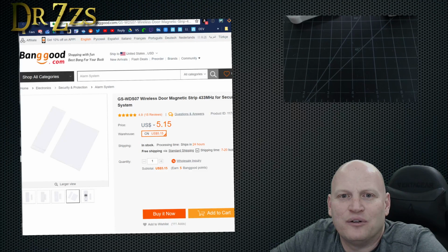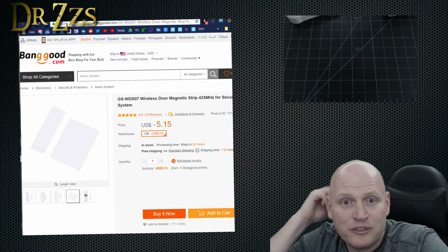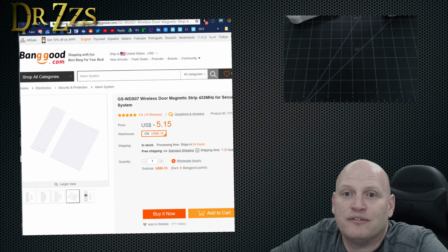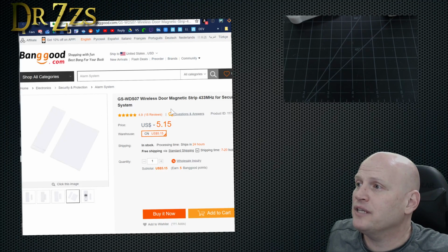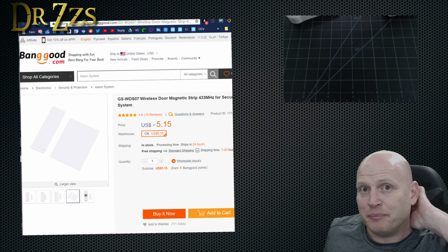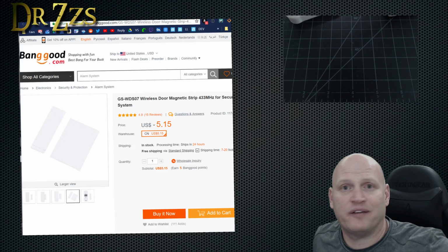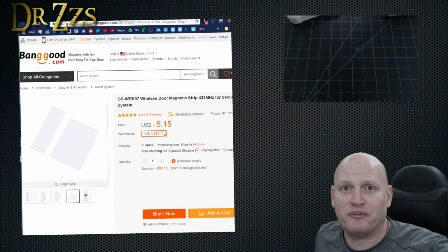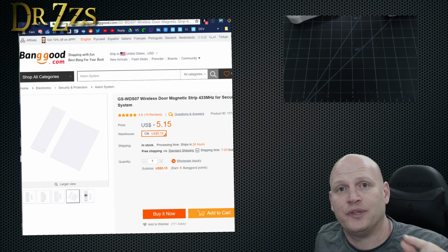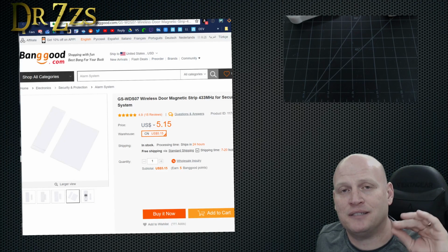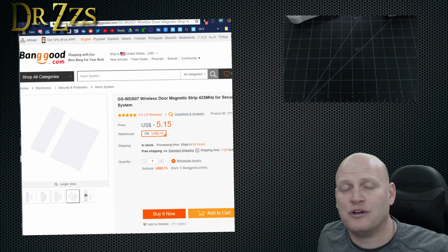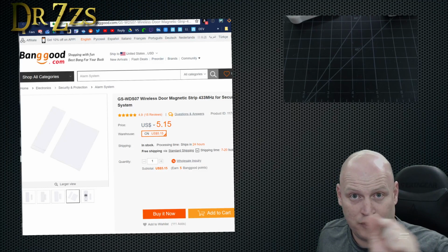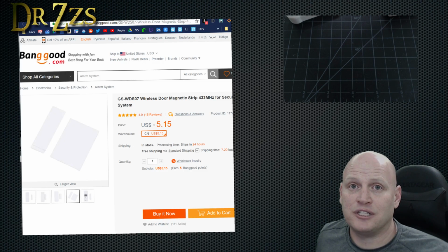Okay, radio hands. Does anyone know if Tasmota supports PWM? Yes, it does. Absolutely does. I can control the individual pins through MQTT by default, but only high and low. As hard as I've looked, I can't see a way to send them a PWM value. If you set that pin in the Tasmota UI as PWM, then when you restart, it will give you a slider bar, and you can slide that bar back and forth.